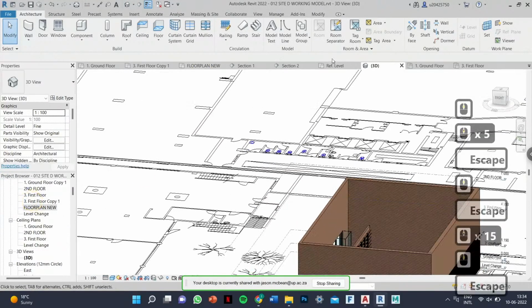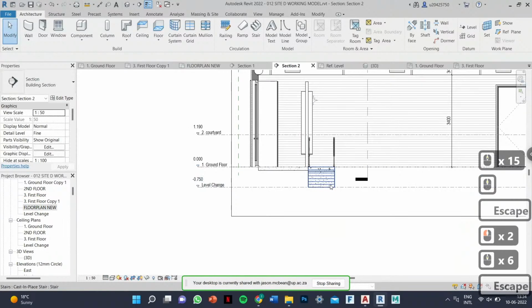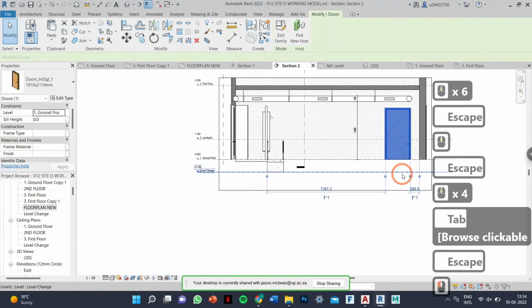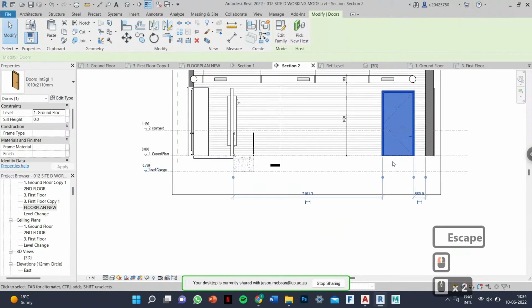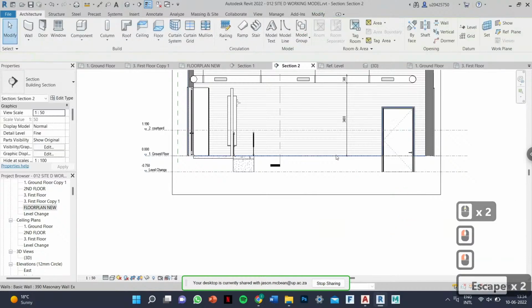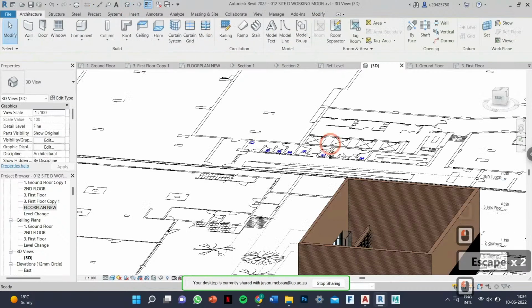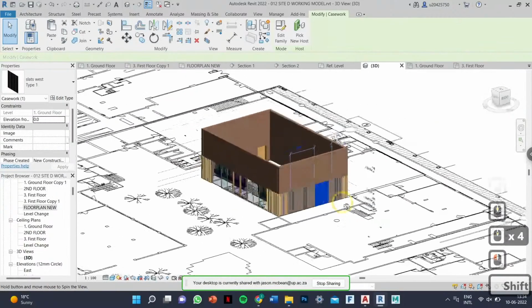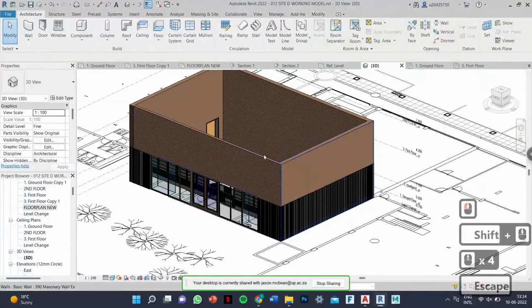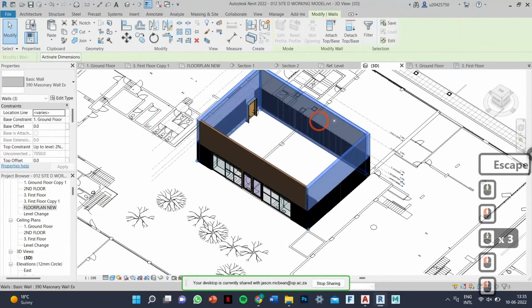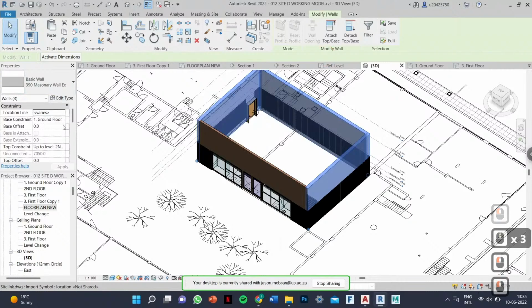We're going to select all of these walls, because technically all the stuff in the background must work with this level now. So you're going to change this to level change. Go to 3D view. I would select all these back walls, all of this stuff. This must work from that. But I'll just use the walls for now. Leave that in place. That must go down from, so location, level change.